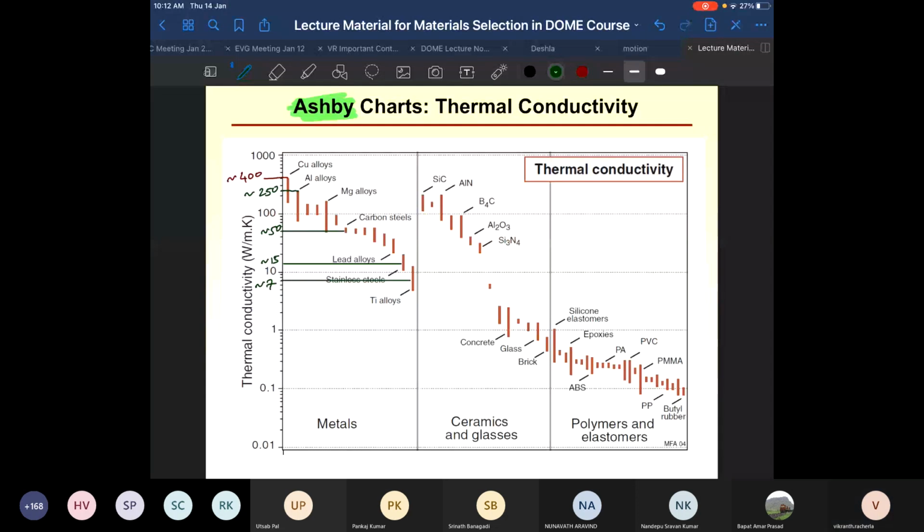Thermal stress. Yes, you would be dealing with very high thermal stresses because you would end up with very strong thermal gradients. So machinability of titanium is a big problem, and one of the reasons is this low thermal conductivity, resulting in some serrated chip formation.